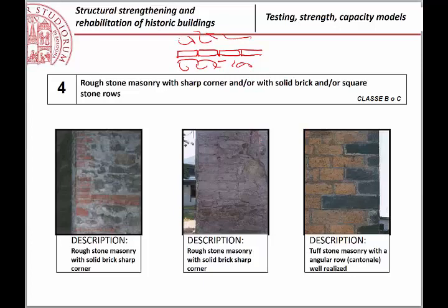If you have just one layer, the strength of the wall with respect to some transverse forces is very, very low, or at least those bricks are not improving, certainly, the strength of the wall transversely, okay? Why? Because there is the mortar between them.